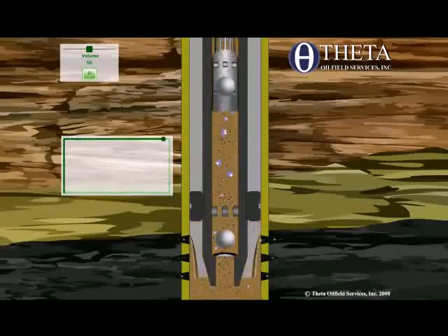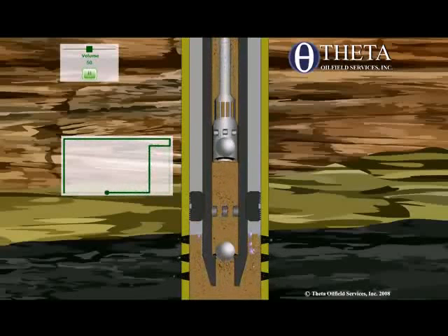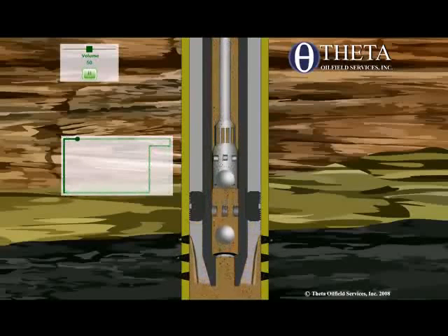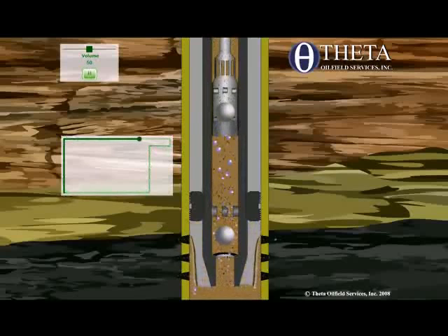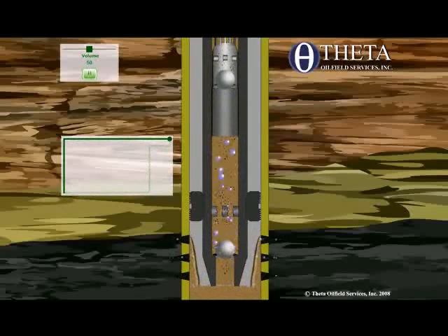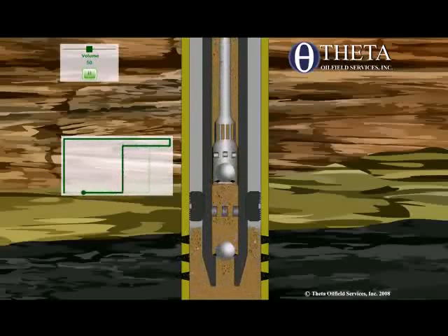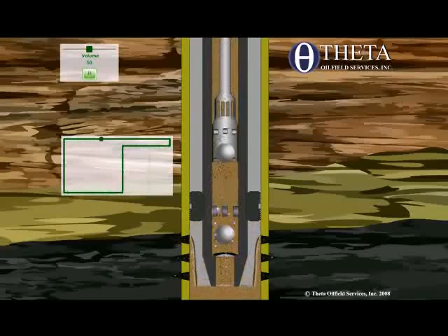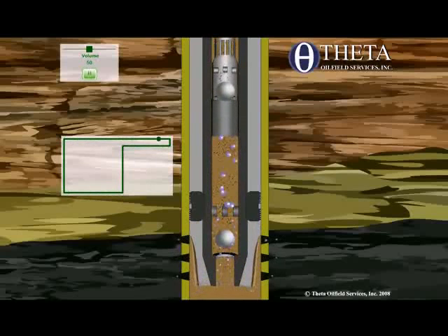See right here, we're almost out of fluid. We're a little bit out of fluid, so we have a slight amount of fluid pound. Now we have more fluid pound. The pump is less full than before. And the same thing happens here.